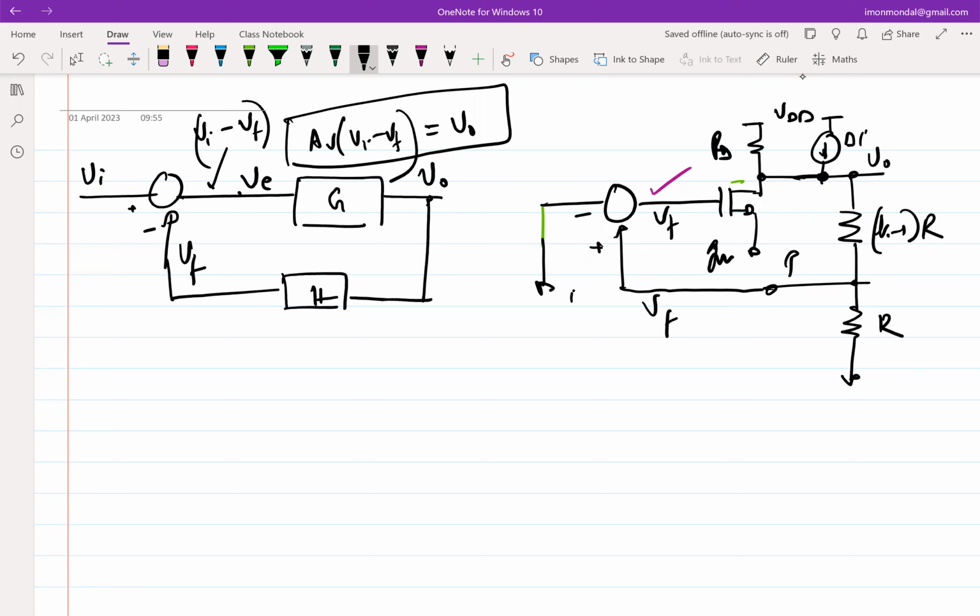Okay, so this is an extremely important property of our negative feedback loop: if you excite the output of a negative feedback loop with any disturbance, assuming the loop is biased properly and designed properly, you will not be able to move the output. This is a good property because it rejects any disturbances when you are trying to disturb the output of the negative feedback loop by any means.